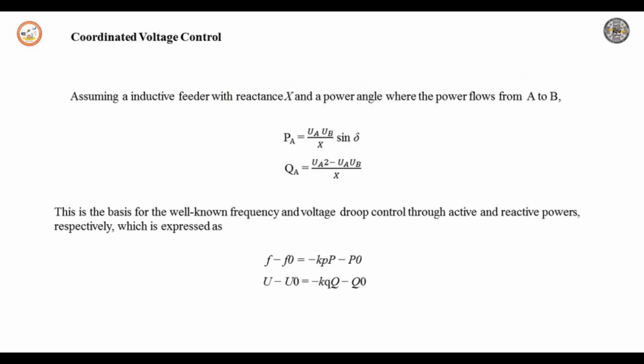So here the over voltage may be curtailed by reducing the power production. It has been assumed that the generator neither produces nor consumes reactive power. When many units are connected in close proximity, it has been shown that the curtailment of an individual generator can be expressed as a ratio of maximum production.